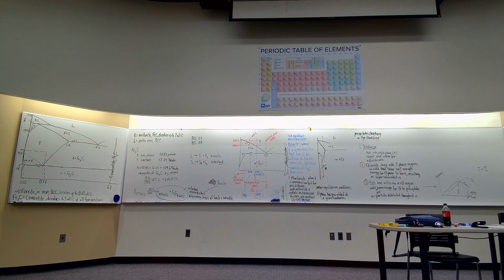And the characteristic that distinguishes these two is called hardenability. Hardenability of a steel is the ease with which you can form the hardest form of steel. Or how likely is it that you can get that? Or how deep into the steel can you get that? Or how likely is it that you could quench in oil and avoid getting cracks by cooling slower?